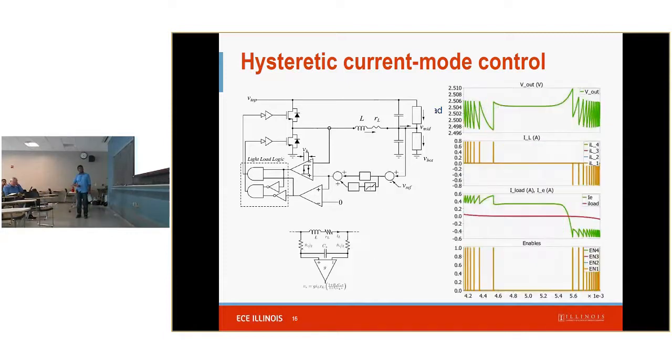So a simple solution is just to use a dead zone with the integral component, so that I reduce my integral gain when my voltage error is too low. So with this dead zone generator, I can get what I want. That is, I have no switching when the load current is below a particular limit, and then again it starts regulating the voltages.